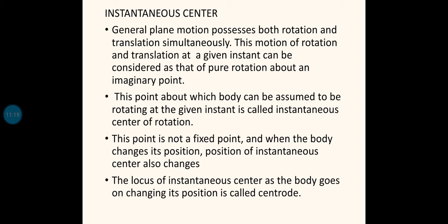So anyway, the definition of the instantaneous center is that plane motion is the combination of rotary motion as well as the translatory motion. But by assuming an imaginary center, we are converting that plane motion into a pure rotary motion about that imaginary center. Such an imaginary center is known as the instantaneous center.